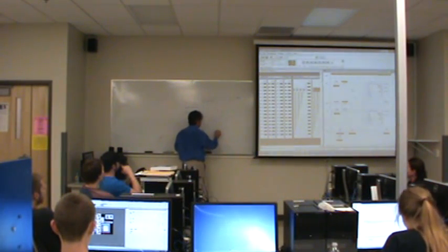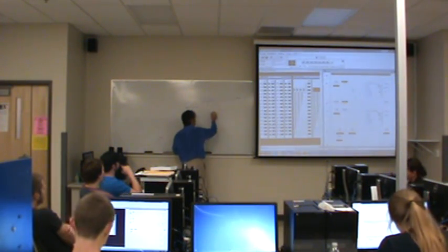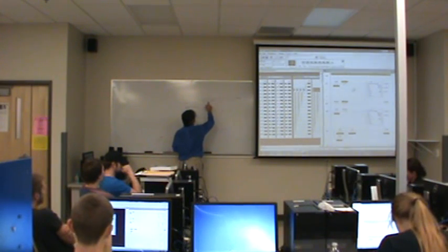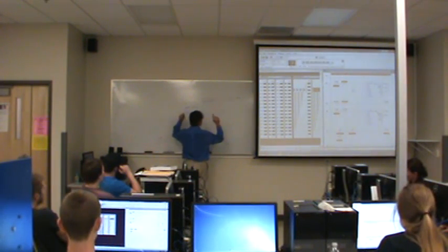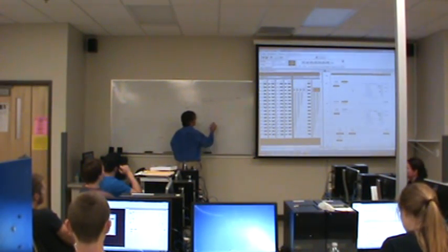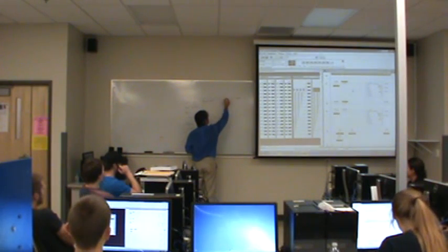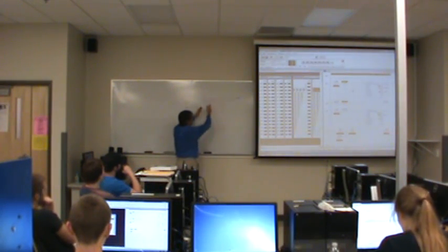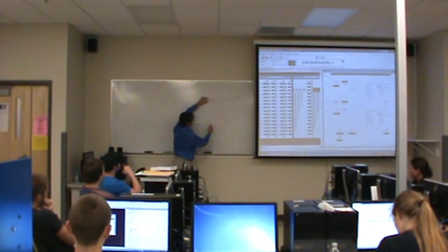And to stick with my integer time steps, I'll have to break this up a little more. So basically for 1, 2, 3, 4, 5, 6 time steps, we're going to have the cold valve on. And maybe if this is the nominally hand wash cycle, then we'd have agitate on for a time step, then a rest time step, then on for a time step, then a rest, and then continue. And so we're going to break up the outputs in time. Okay. So what I have to do is somehow program all of this into memory. I have to have ones here, zeros everywhere else for the other outputs, and 1 here, 0, and so forth until I get to here.